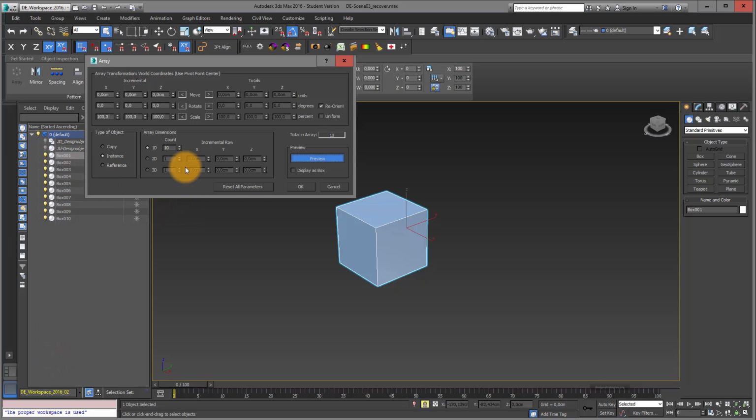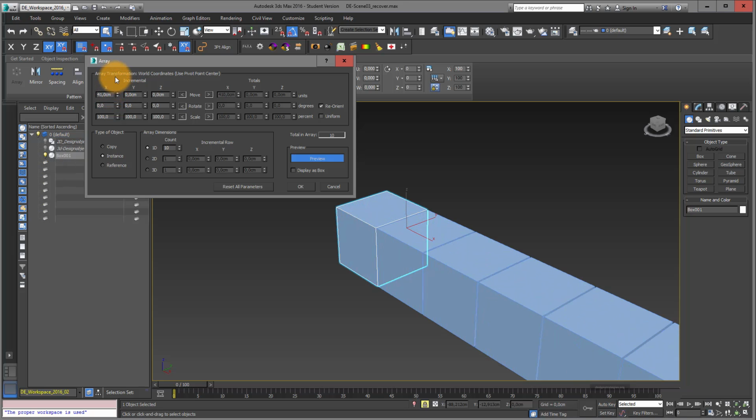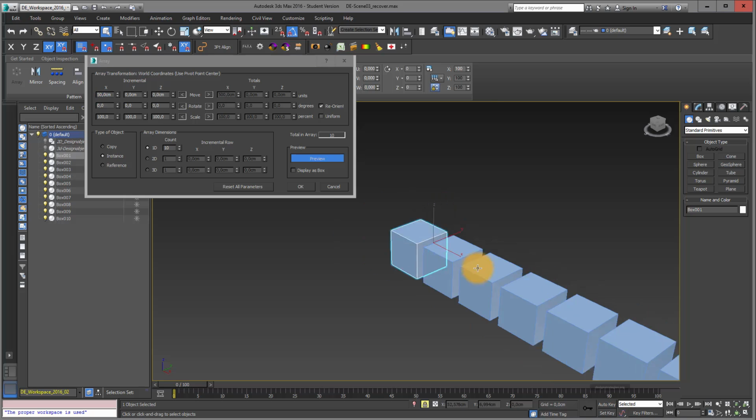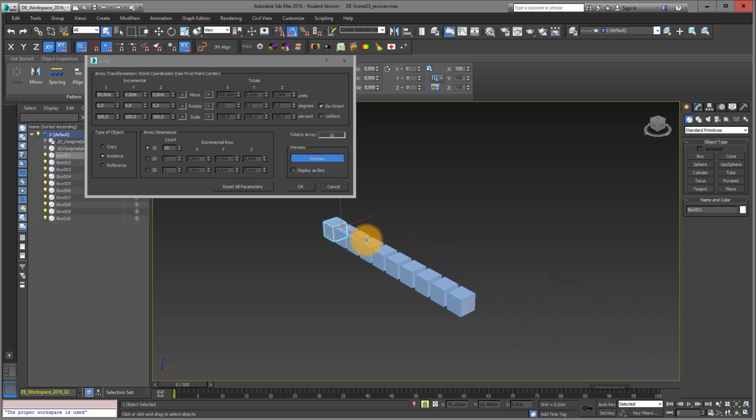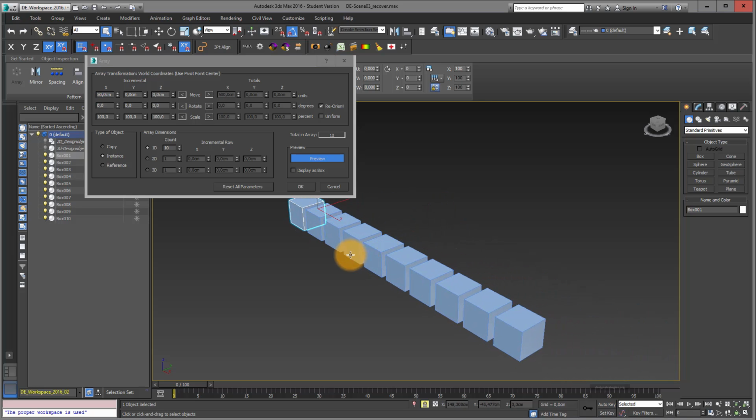You can't see it right now. If you want to see this, then you probably move this. I just move it into Z direction. I just have a look what kind of amount is appropriate, and just move it with 50 centimeters, press enter, and now they moved 50 centimeters in one direction.